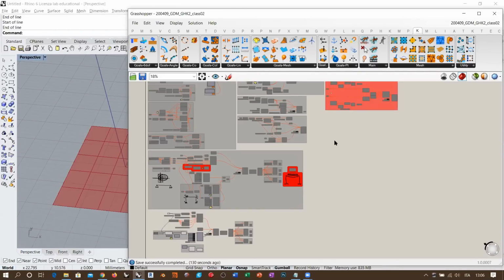In that case, there is some optimization occurring naturally in the use of Kangaroo, but it's just because the system takes its equilibrium shape according to the loads and the restraints that you are providing. But what you're talking about, optimization in terms of the amount of material, just keeping the structure as light as possible, has to do with a different theory, which is called topological optimization. And if you want to explore it, what you can do is start playing around with